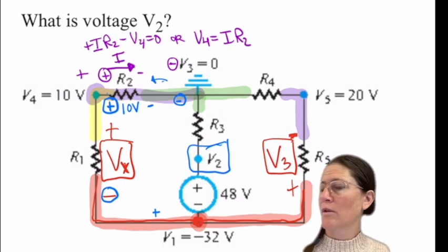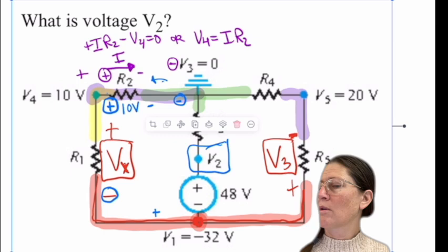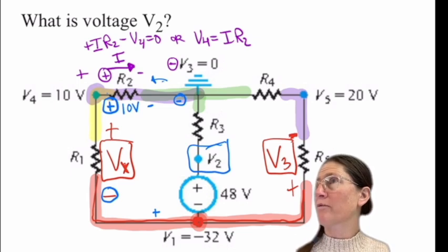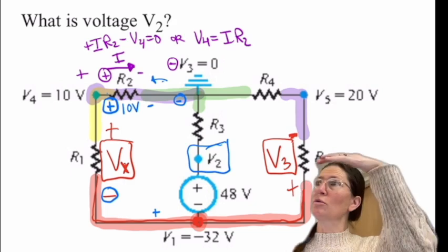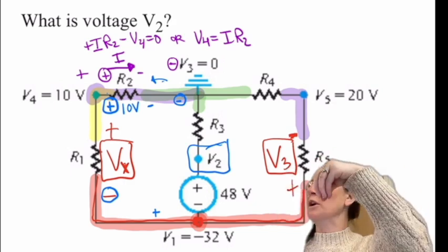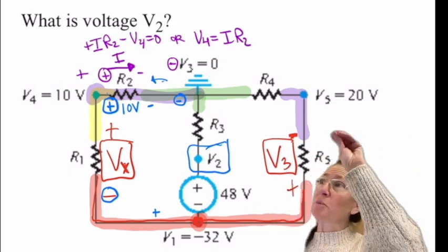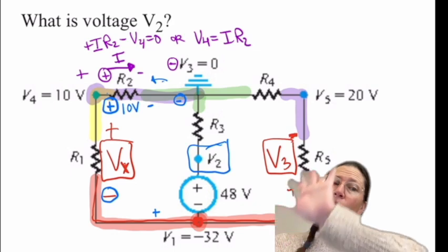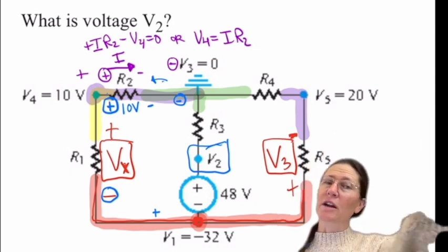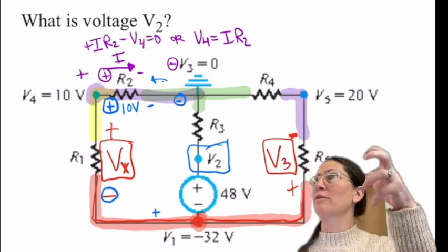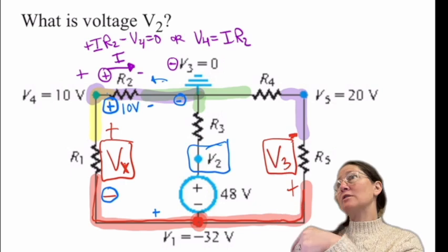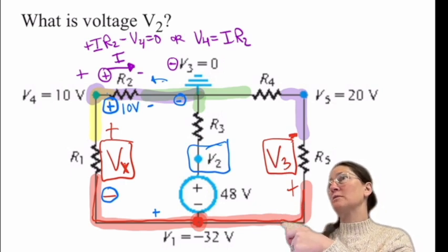But when you do voltage, you're not adding up and moving to zero like a KCL. It's a different thing. A KVL is where you take a loop from one point back to the same point. If you're going through different branches, that's getting you back there. So I go through R2 and then through V4, which is a physical multimeter. So they're different branches getting you back to the same point.